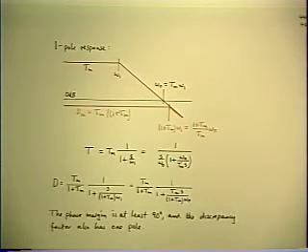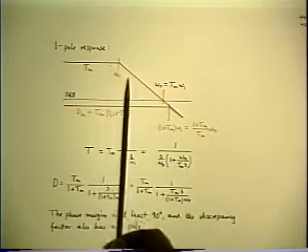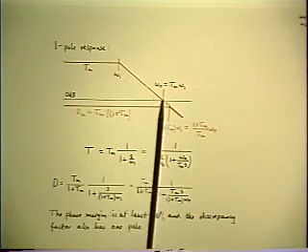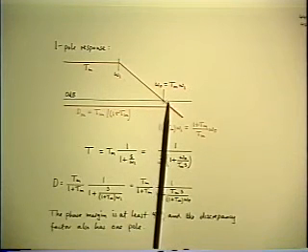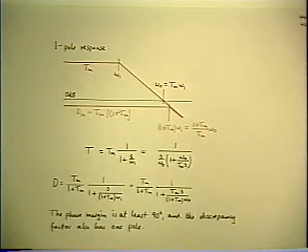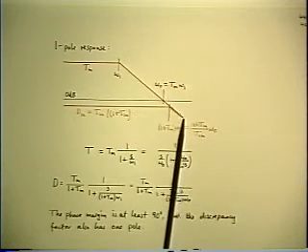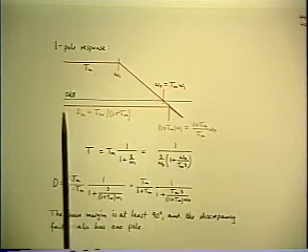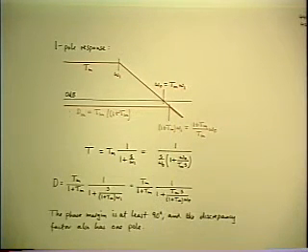About 90 degrees. Assuming you're far enough down this slope, the phase angle of T is almost 90 degrees, which is 90 degrees less than the critical 180, so the phase margin is 90 degrees. Just qualitatively, we associate a phase margin of 90 degrees with an almost ideal shape of D.